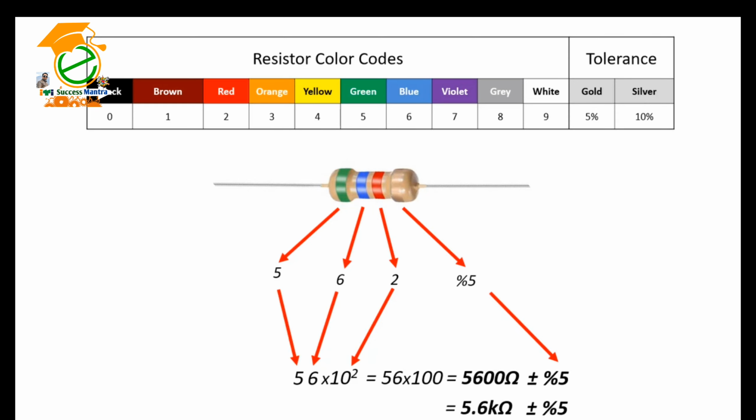Any resistor of over 1,000 ohms is typically shortened using the letter K. For instance, 1,000 would be 1 kiloohm, 3,900 ohms would be translated to 3.9 kiloohms, and 470,000 ohms would become 470 kiloohms. Values of ohms over 1,000,000 are represented using the letter M. In this case, 1 million ohms would become 1 megohm.